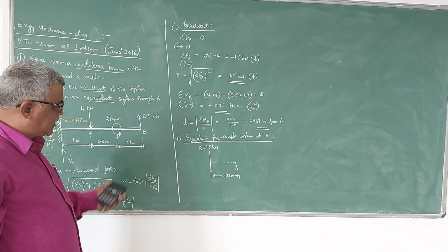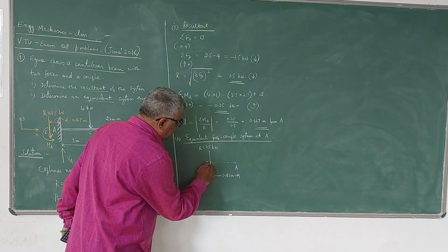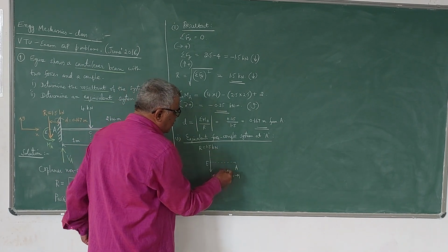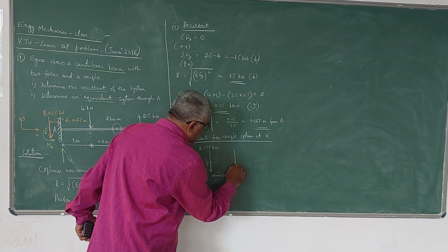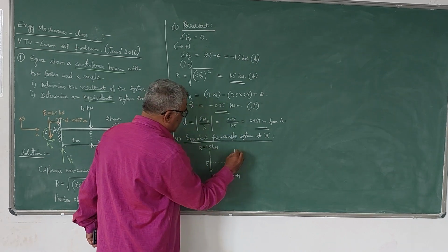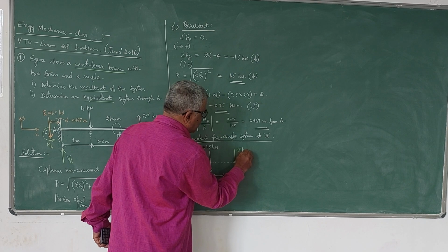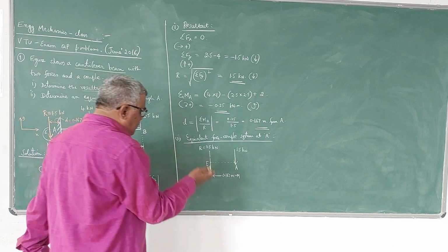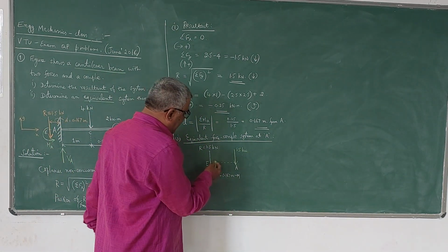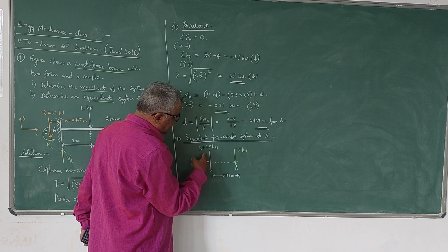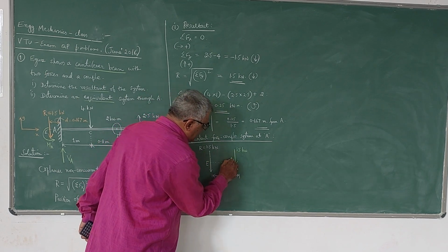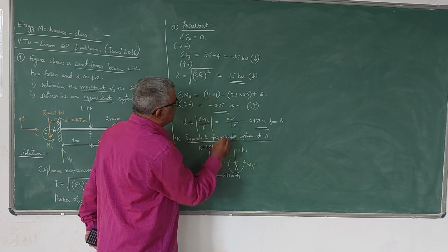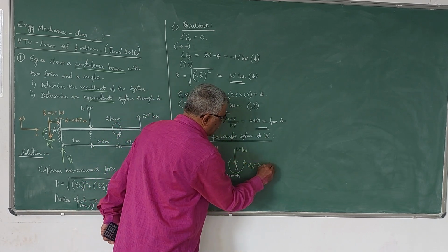Now I want to transfer this over here. I have told you that whenever you want to transfer this force to here, we introduce the same force here at the point in the same direction, that is 1.5 kN force is transferred to the point A. In addition to that, we have to take the anti-clockwise moment, because this R is giving an anti-clockwise moment about A, like this, MA value, which is 0.25 kN.